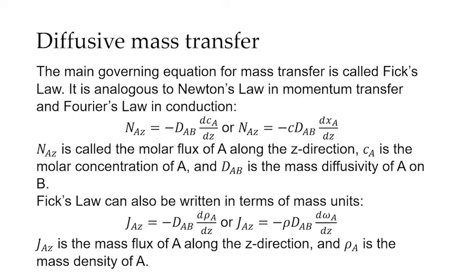The main governing equation for mass transfer is called Fick's law. It is analogous to Newton's law in momentum transfer and Fourier's law in conduction. We have here a generalized equation of Fick's first law. N_Az is called the molar flux of A along the z direction. Take note of the subscript.